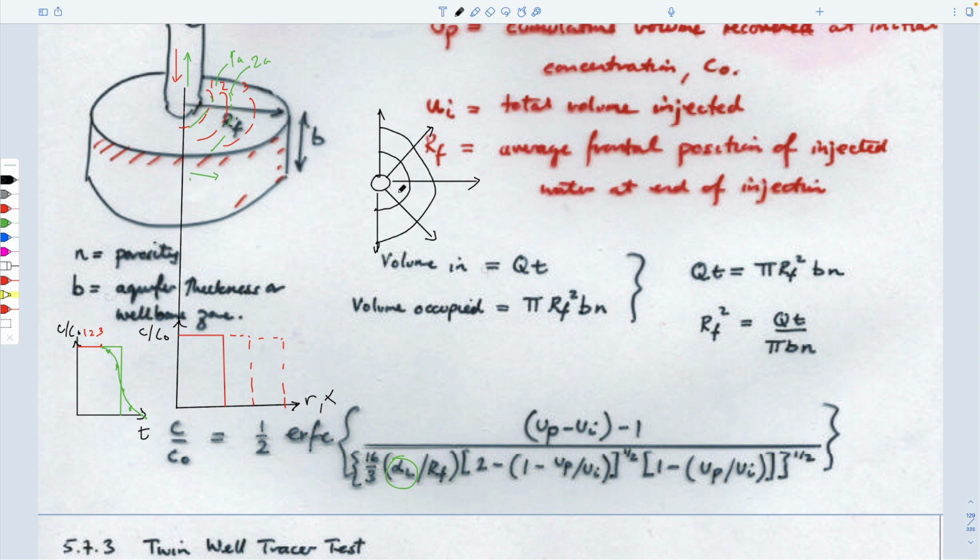You see that as you go from this point to here, you must by definition have a big velocity at this point and a relatively small velocity here, because it's going across a bigger cross-sectional area, just by continuity, right? Same volumetric flow across each of these interfaces. This interface is small, so the velocity must be large. This interface is large, so the velocity must be small.